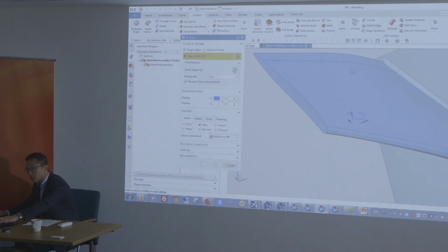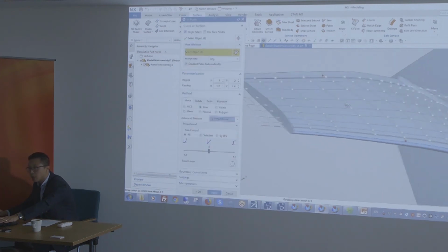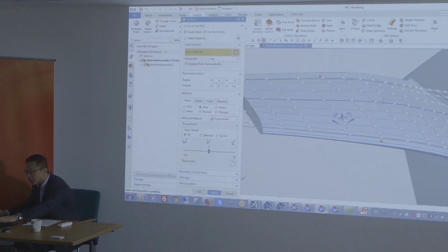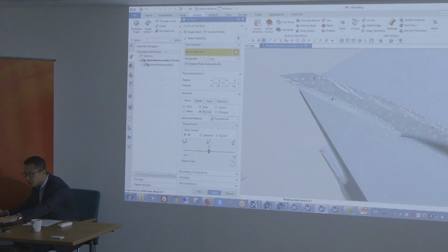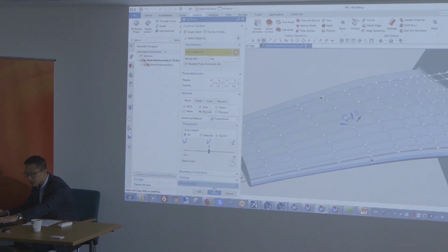So you can go here, right? Then you see there are a few grid points spread out through my face, so it recognizes the different edges, the different points. So I can take that geometry here, and just push that edge a little bit. Okay, so it changes the curvature. You see the original one. I'll pull it a little bit more, let's say from here. Okay, so let's apply that change.